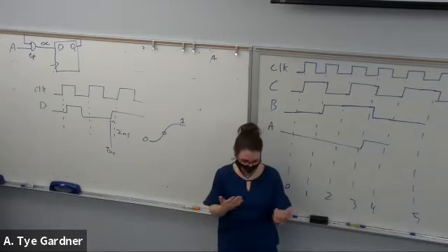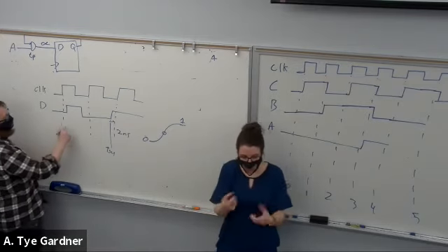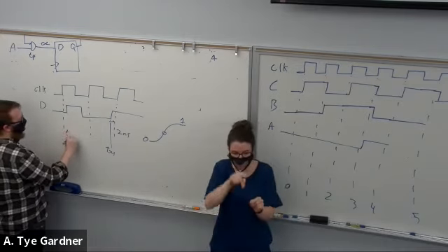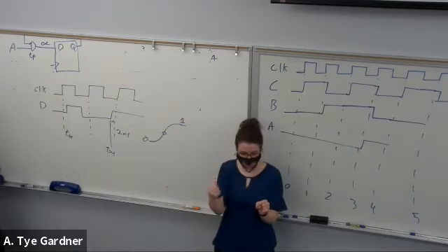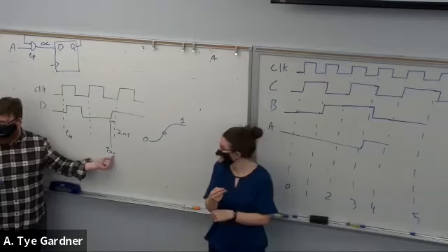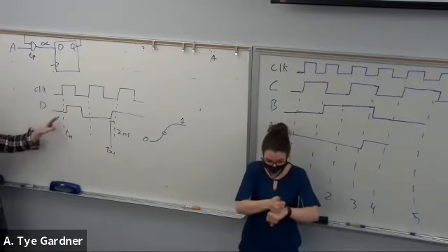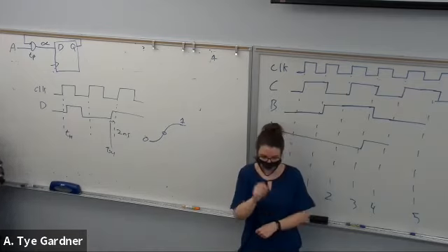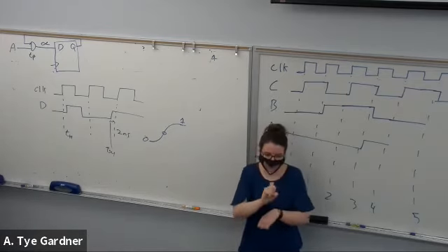That is setup time. The same issue happens on the other side of the clock, and we call that hold time, or TH. You'll occasionally see setup as just TS. I like to do SU, just to be a little more clear. So hold time is the amount of time that you need your inputs to be stable after the rising edge of the clock.